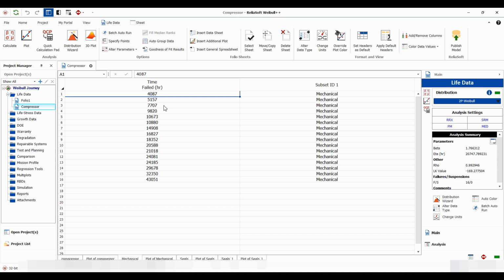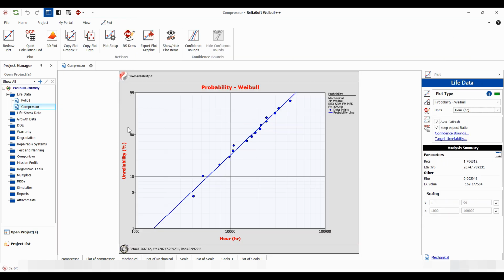And the other thing is also the graph itself is very informative. Here we have the graph on the Weibull paper. Based on how the points align with the model, which is the blue line, we are able, first of all, to establish whether the model is valid or not, but also whether there is some behavior that could be linked to different types of failure mode interacting, or whether there is a batch problem, that kind of problem. So that makes the statistical method much more practical in its use.